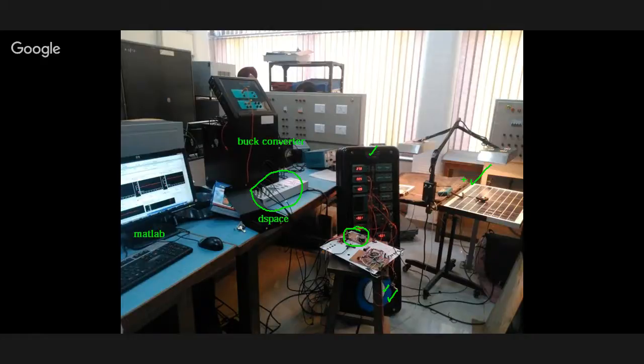So what we did is this 17 volts we reduced to 1.7. For that we used a potential divider. We used 2 resistors in series, and we divided the voltage. Around 16 volts we dropped, and only 1.7 volts, dropped across one resistor, that 1.7 we took inside, we multiplied by 10 and we got the 17 volts inside our software. So that should be kept in mind. You cannot take the voltage as such inside.